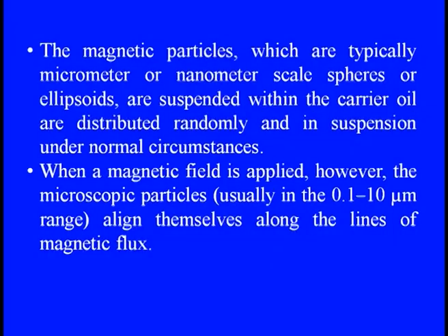But when the magnetic field is applied, even the microscopic particles, in the range of 0.1 to 10 micrometers, align themselves along the lines of the magnetic flux.